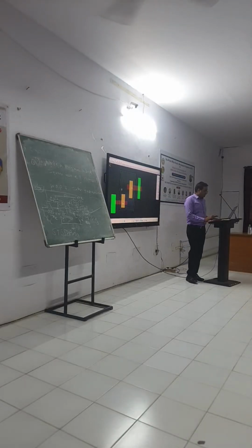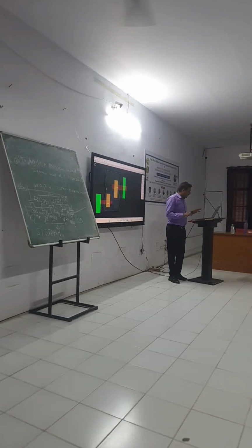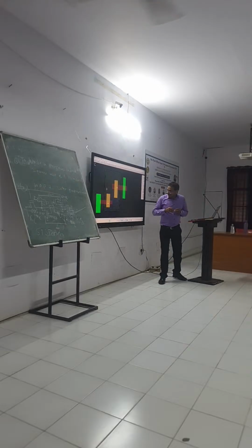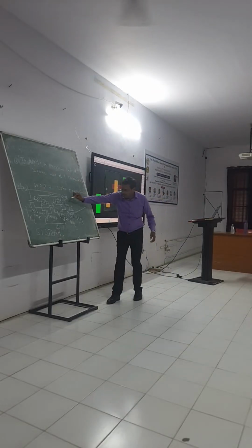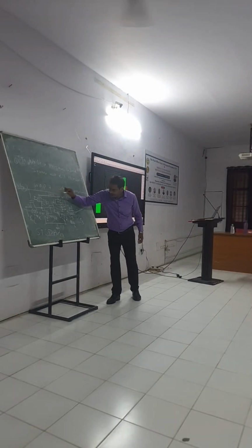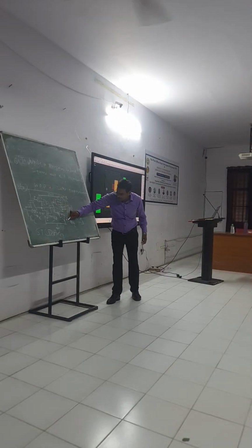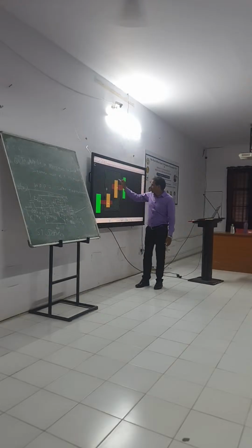Okay. So see, two PMOS I designed like MP1, MP2. So see, based on that circuit connections, this is your PMOS MP2. First I am talking about this MP2. Its source is connected with VDD, drain is connected with the drain of NMOS. Okay, so this source you keep here. So source is nothing but VDD.